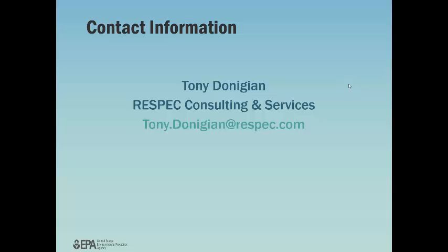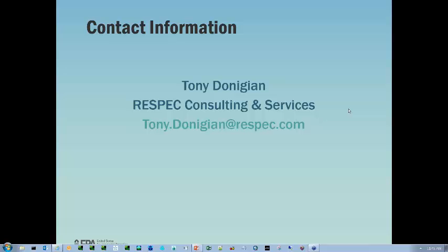Okay. Transition zones, I guess, are more an issue of how well you discretize your stream channel in those areas and the associated contributing area. Yeah, you can. There's no limitation really in terms of the size of stream segments you have. You probably need smaller temporal resolution, more detailed simulations. You might need to run the stream channel in 5 or 15-minute increment mode, depending on the size of your watershed. It's important to see what's happening in that transition zone. It's not going to give you backwater type things, where the level of the reservoir should back up into the stream channel. It doesn't represent that phenomenon. You would need a more detailed hydrodynamic model to really handle that.